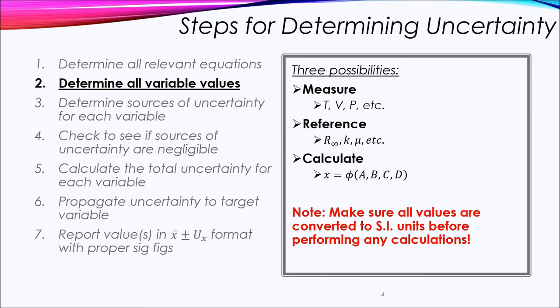Now, make sure when you're doing these calculations that you convert all of your values over to SI units, or if you happen to be using another form, make sure that they get converted to that. Before you do any calculations, it doesn't actually matter the order, you can always figure it out later, but it's usually safer to just do it right away, and therefore you don't get any mistakes where you actually didn't convert from inches water to pascals, and that destroys your equations and values down the line.